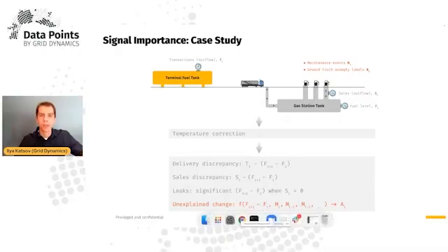And it was possible in this case to build essentially a supervised model that could be used to predict these anomalies based on the observed events and maintenance events. This model could be used to reduce the number of events that need to be monitored, because some of them are important, some of them are not. Using this technique with anomaly prediction, we basically can reduce the amount of signals that we need to monitor even further compared to just usage of the system model.